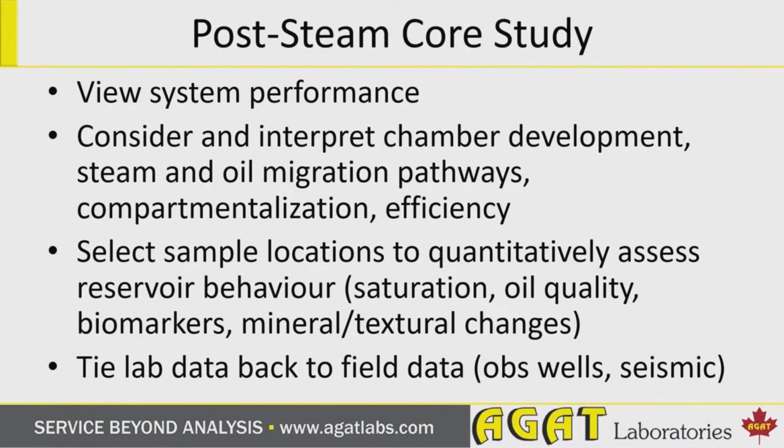So just to sum up, a post-steam core analysis study is really to help us understand system performance. We want to consider and interpret the chamber development, and we want to observe the steam and oil migration pathways and try to theorize about how those pathways develop and how they might behave over time through a reservoir. We want to try and investigate reservoir compartmentalization compared to any of our predictions about it, whether we actually see what we thought might happen.